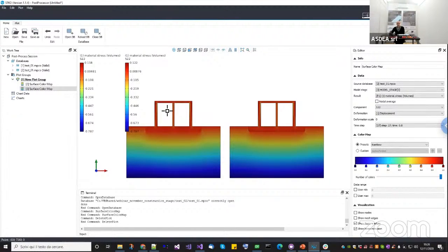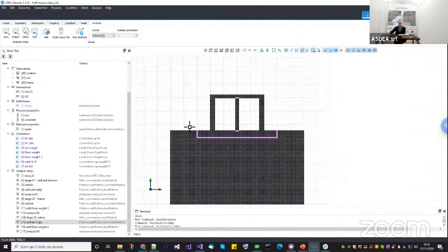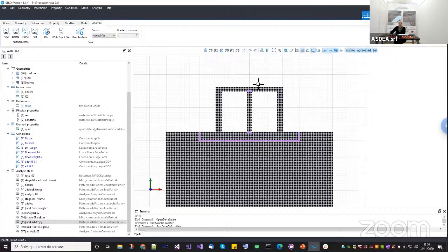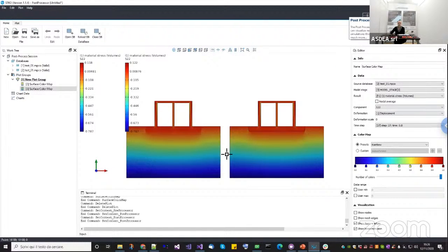And the problem is that, especially for people doing construction stage analysis, the concept of initial state analysis cannot be applied to beams. So the problem is that now in my case, I model the frame as solids, but typically this superstructure will be done with beams or shells. And in that case, it will not work. While this approach of kinematically constrained subdomains will work for any kind of material. And the other nice thing is that since here the displacements are not reset to 0 instantaneously, this one will work without any problem also in dynamic analysis.